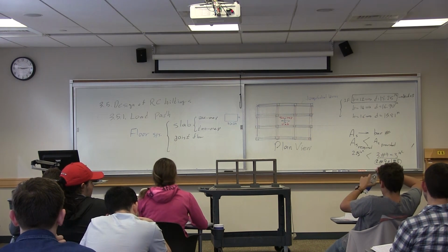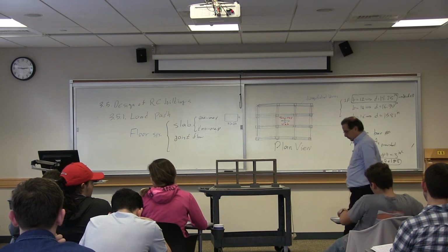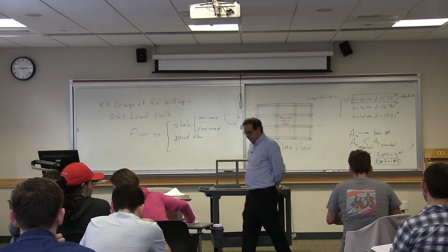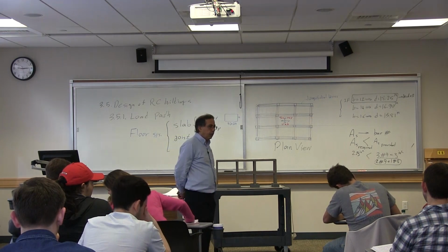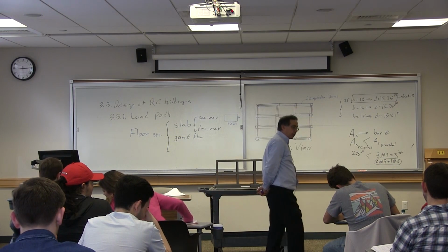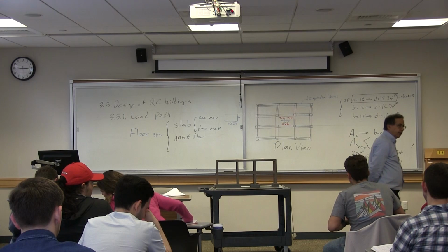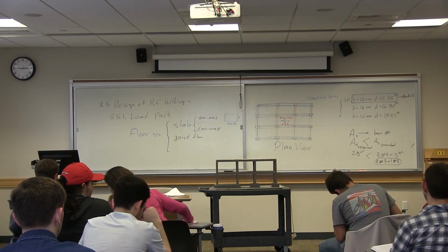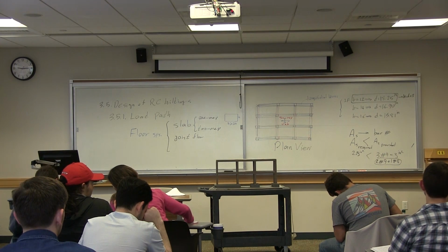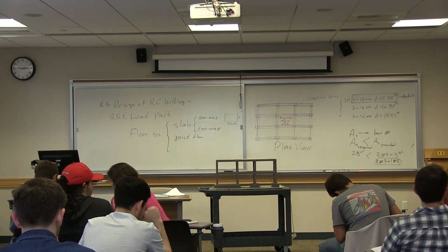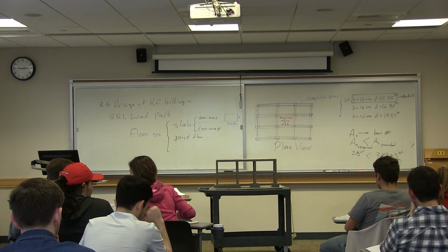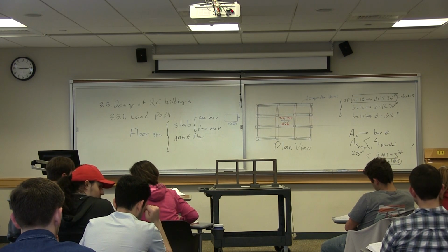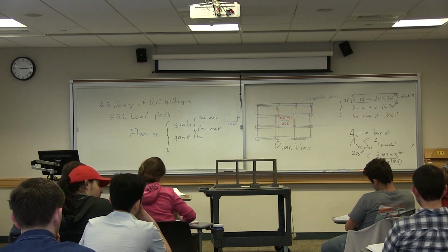Because the distance between the center of the slab and the extremity of the longitudinal part of the slab is smaller than the other. Why is that distance important? Because that's the distance that the load has to travel. And then why, when it needs to travel more, would it travel less? Because it would find the easiest path for travel.